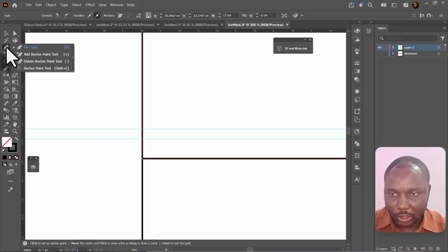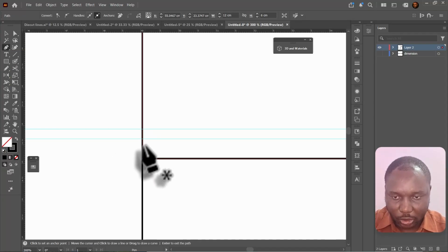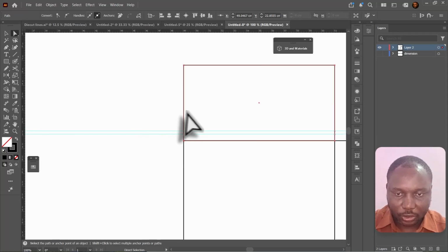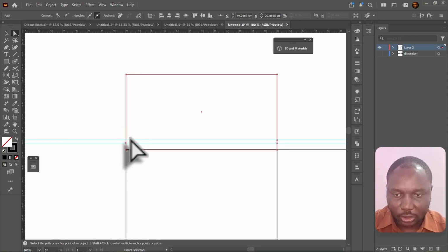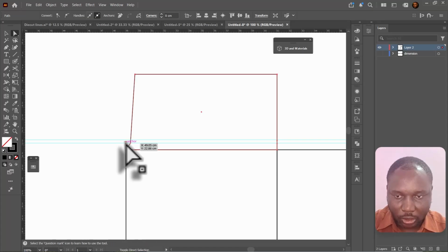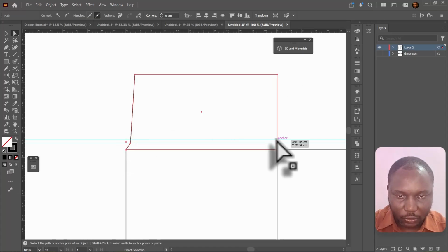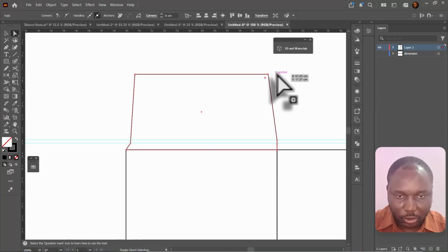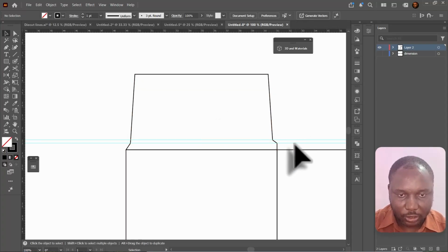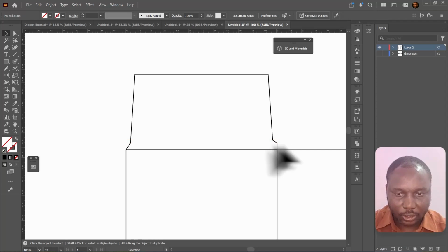Here we're going to add just one anchor point. You can select either the pen tool or the add anchor point tool. Either one is fine. I can click here to add an anchor point. Use A to move it to this point right here. That's basically all I need to do. So I'll select this. I'll move it twice, 1, 2, and then this I'm going to move just once. For this I'll move it twice first, 1, 2, and then this I'm going to move once, like that. I'm going to have this selected. I'm talking about the guide, so I'll delete it.